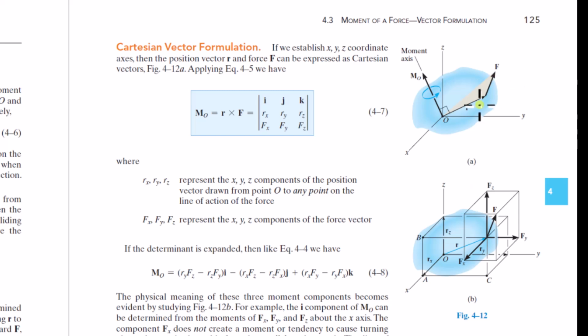If you're calculating the moment of a force about some axis you pick, the moment about the x-axis, or the z-axis, or this axis, then it's a sliding vector, because think about the context. The moment of the force about a specific axis is the same no matter what point I choose on that axis to calculate the moment. You can slide that moment without changing the problem.